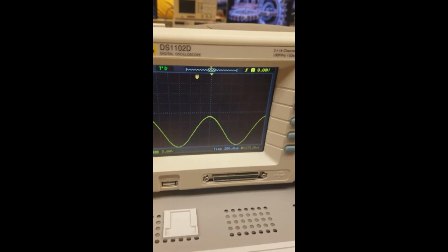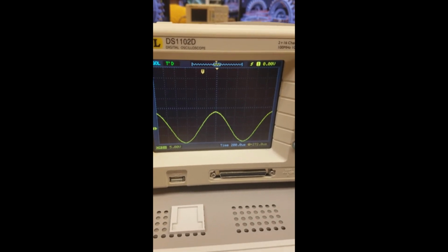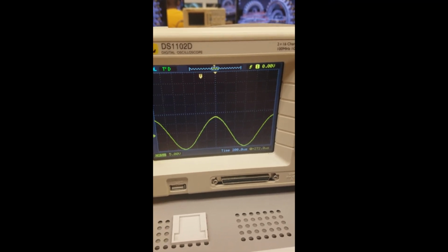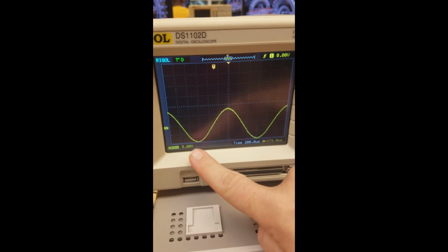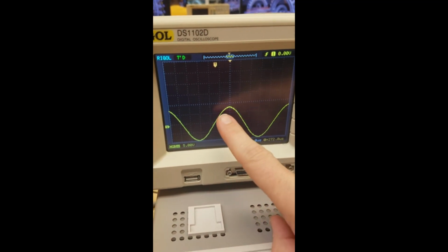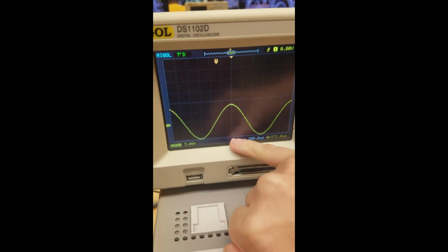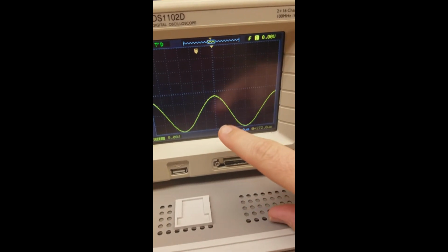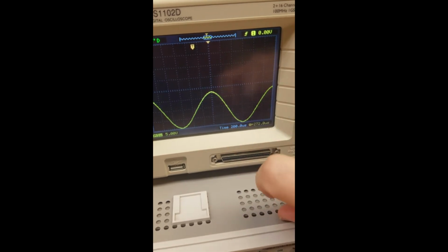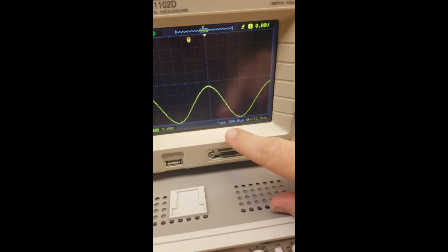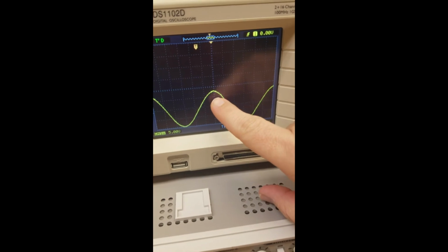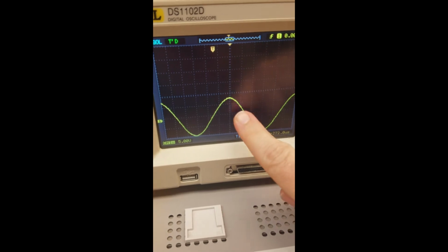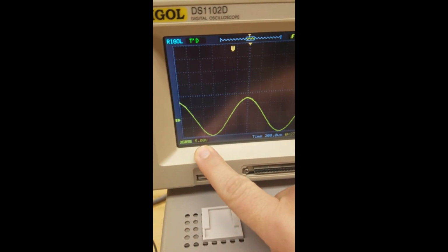And once we do that, we get 806.45 hertz. I'm going to find the VPP, the peak-to-peak voltage for channel 1. First, I position the sine wave so it's at the bottom of the screen, and that the peak is at the middle, right in the center. Alright, so to do this, what we do is count the number of squares going up, because voltage is the y-axis. We have 1, 2, 3.6 at 5 volts per division.